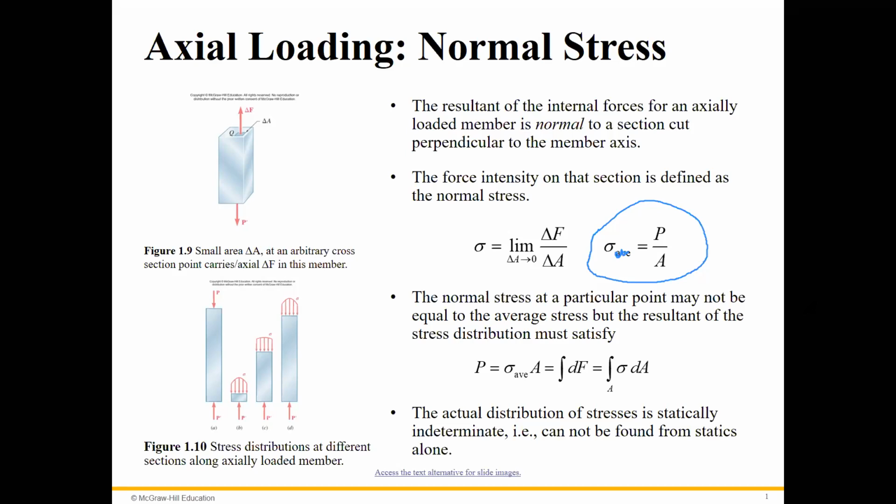And then we apply the loading, and after that it elongates, and then it fails, right? Then based on the force applied to these cross sections, we can find the maximum or allowable stress. And that allowable stress, or maximum one, is a criterion.